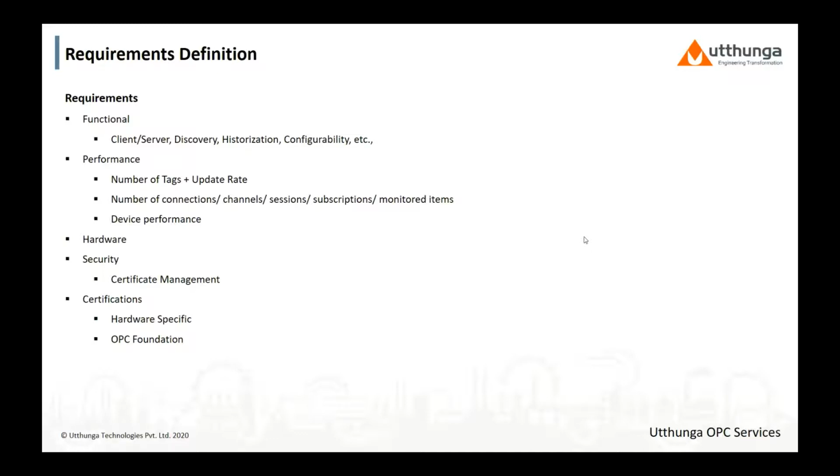And based on this, again, hardware requirements in terms of all the different certifications, all the CE certifications and intrinsic safety certifications and so on, and security, whether you want to have security of OPC UA enabled on the device or not.